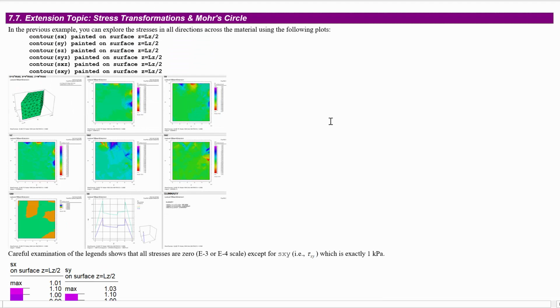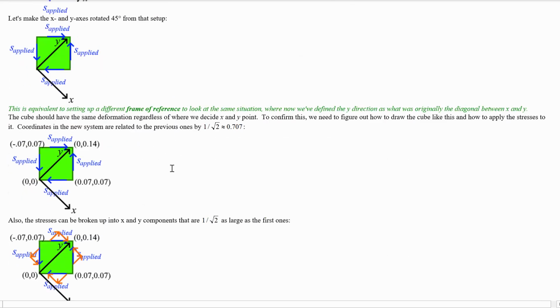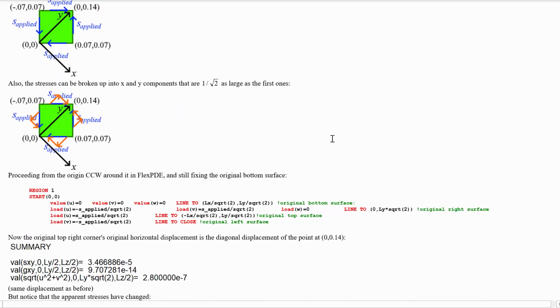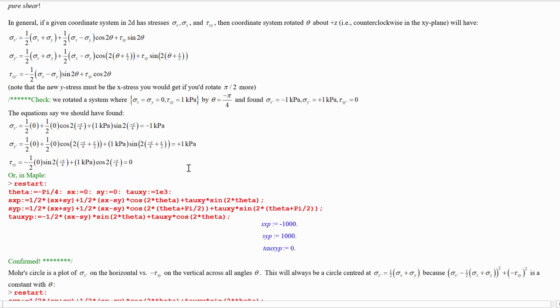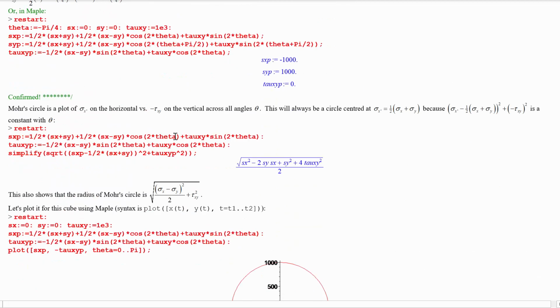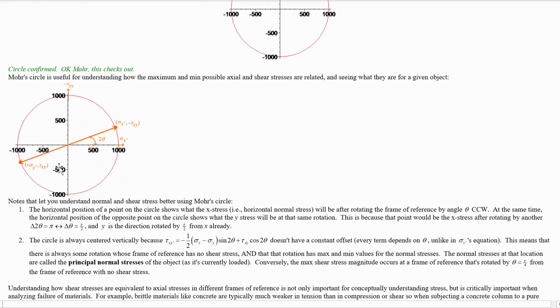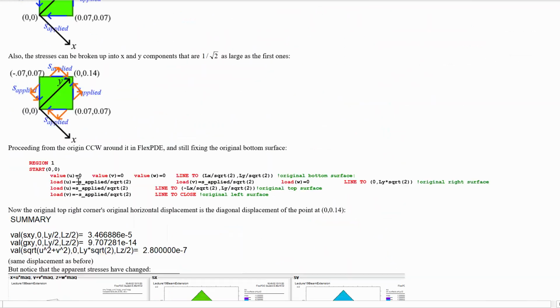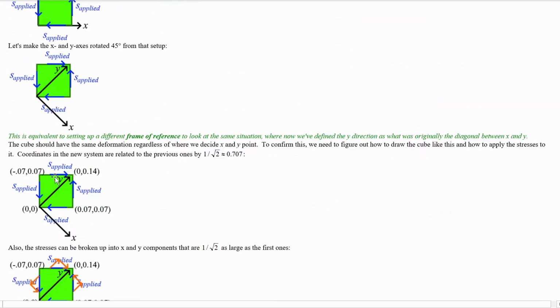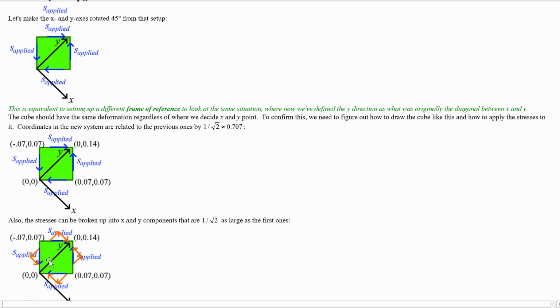All right, so this is really just an expression of the idea to help explain what shear and axial stress really mean. When we put a thing into pure shear static equilibrium, there's some other orientation where that same loading condition could be achieved with just normal stresses. This is very important if you're looking at failure of materials, where you've got, let's say, a brittle material that is much weaker in tension than it is in shear or in compression, because the pure shear that we have in one orientation turns out to be tension and compression in another orientation.